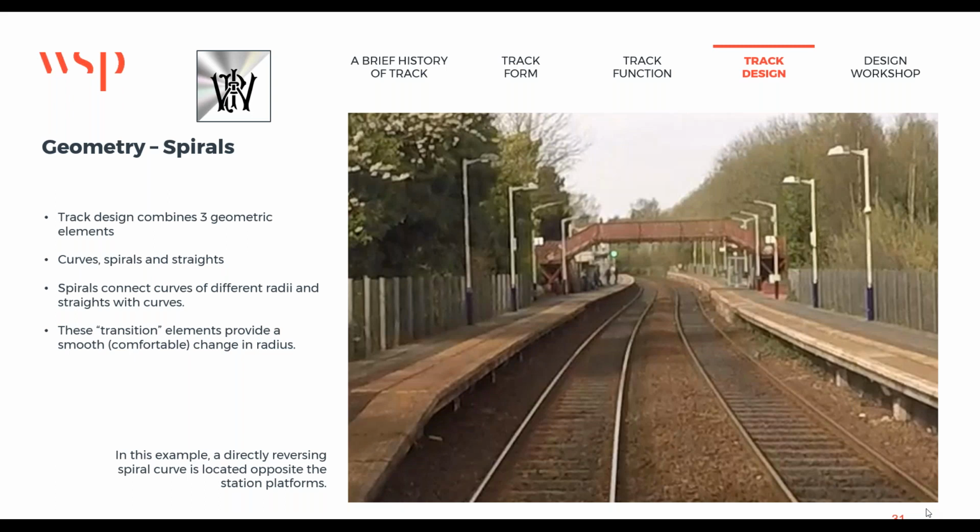No, I do travel on the front coach of the Pendolino, a little short coach because it's normally got catering on it too. But that and the Voyagers, you do feel them, and that's just the lag. So the system isn't reading the track ahead; it's reading the track beneath itself. There is a little lag as the system detects that it's on a transition, going on a curve, or coming off a transition, going on the straight, and it's trying to adjust very quickly the inclination of the carriage correctly. I'm not really too sure about the smarts involved in that, but obviously there's microprocessors involved,